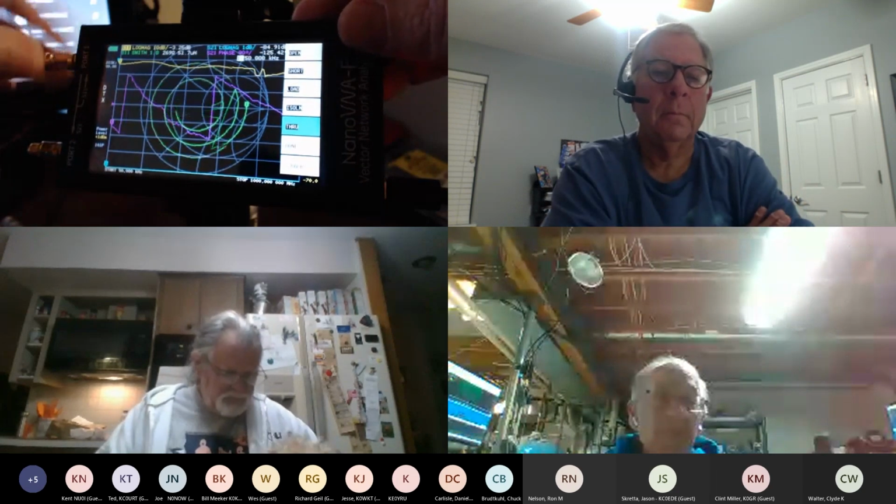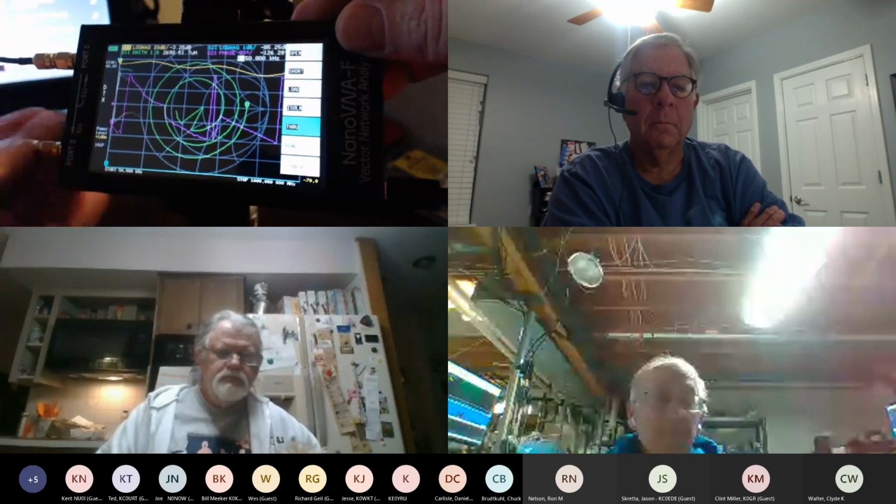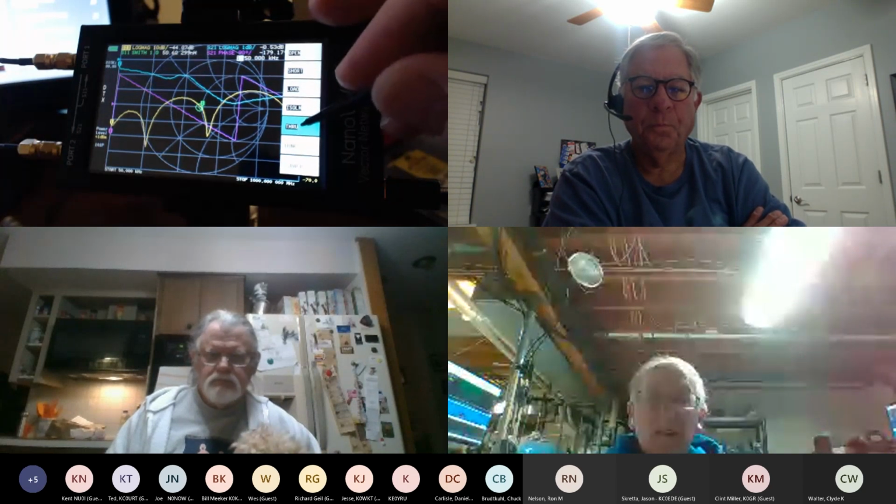So we're actually going to go from port 0 to 1 or 1 to 2, depending on how you look at it. All I've got here is just a simple piece of Teflon coax with SMA connectors on each end. And we're connecting from one port to the other. You'll notice here on the side as we've completed, we've now got DT and X. This is going to balance out the rest of the calibration for us. So we calculate the through, we tell the instrument that we're done.